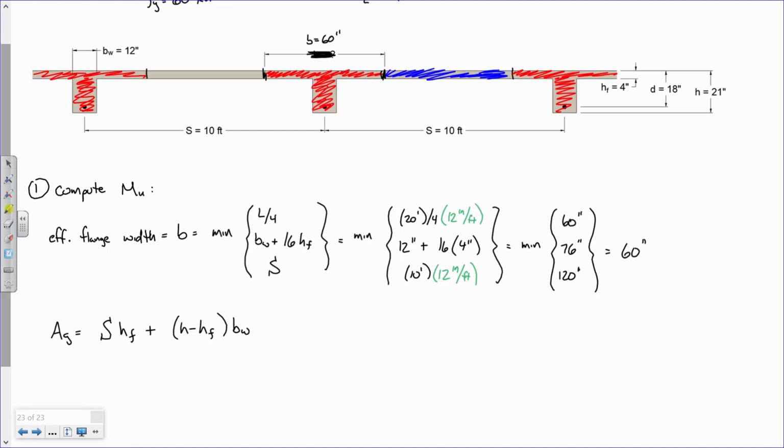Finish that out. Remember, the S only covers halfway between the two. What I'm saying is this: this T-beam in the center is responsible for this, and then the next T-beam over is going to be responsible for the other half and the other half. See what I mean? So what I'm getting at, we don't get to count on that blue slab for resistance, but we have to count on it for load. Does that make sense? Yes.